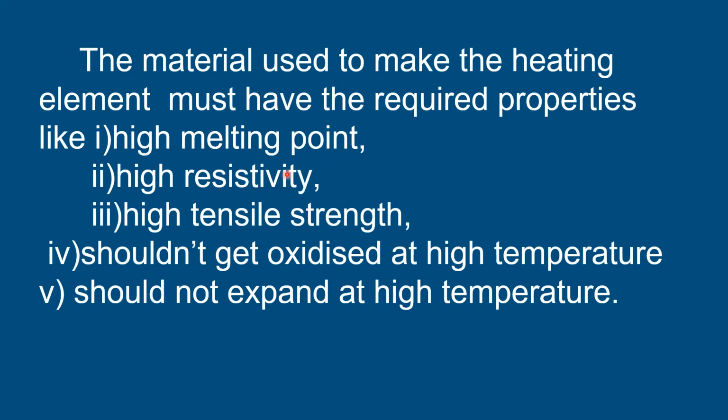Then the next property, high resistivity. Why should the heating element have high resistivity? The larger the resistance, the larger is the amount of heat it can store. So it should have high resistivity. The next, high tensile strength.